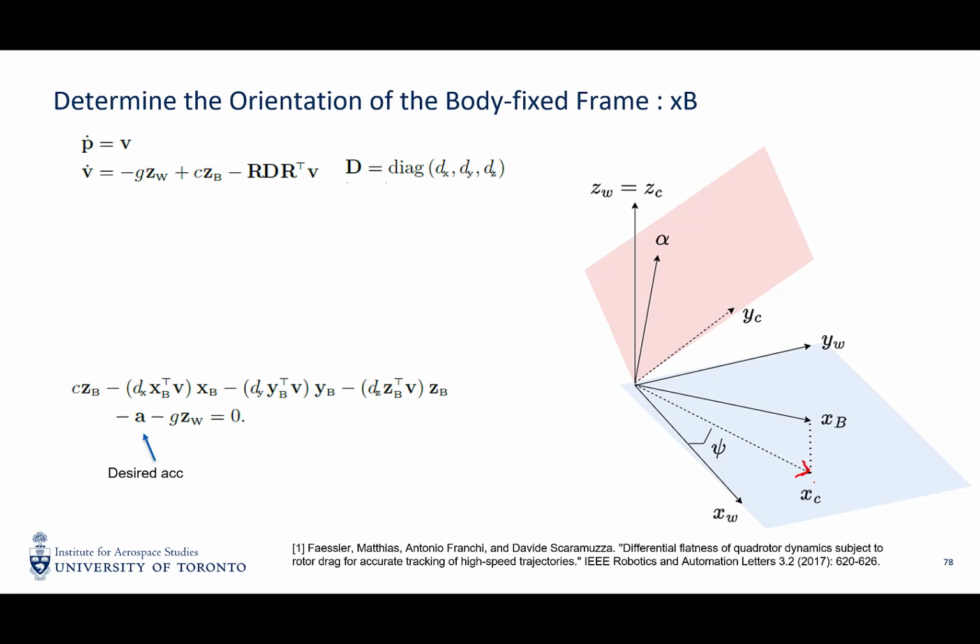Since XC is determined by the heading angle psi, we constrain the x-axis of the body fixed frame so that the projection of xb onto the xw yw plane is the same as xc.